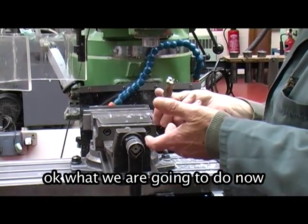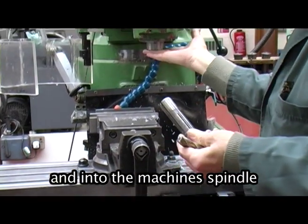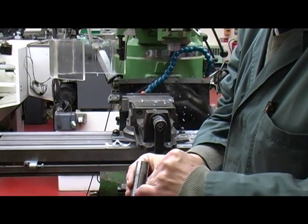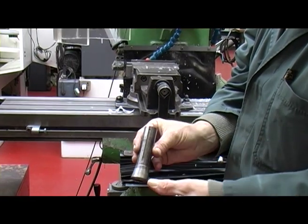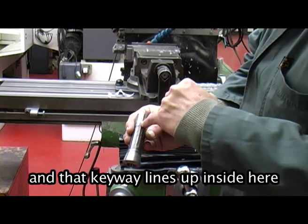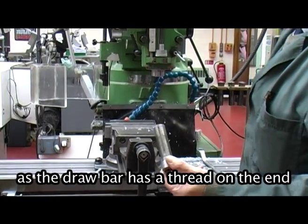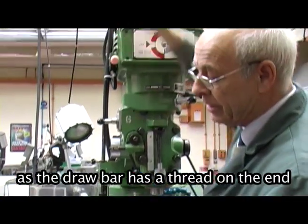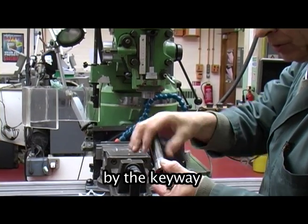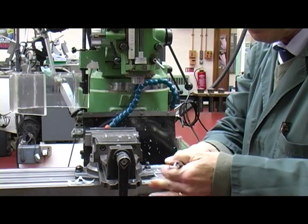Okay, what we're going to do now is assemble a cutter into a collet and into the machine spindle. If you have a look at the collet, there's a keyway and then there's a thread in the end, and that keyway lines up inside here. As the drawbar, which has a thread on the end, screws the collet up, it is prevented from rotating by the keyway, and then pulls in and clamps onto the cutter.